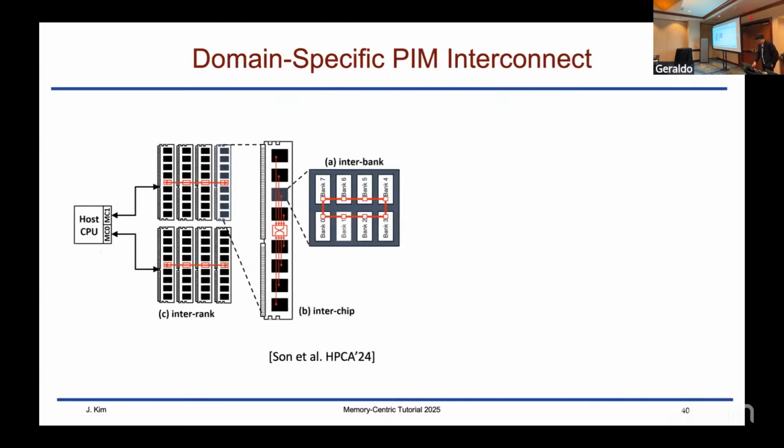So this is where we propose what we call the PIMNet. This is what my student will be presenting on Wednesday, where you could propose interconnecting the PIM units together. You could have a PIM interconnect at the chip level, at the DIMM level, and across the DIMMs as well. Each of them would have different constraints and different ways of communicating, but effectively, it prevents you from having to go back to the host for communication.